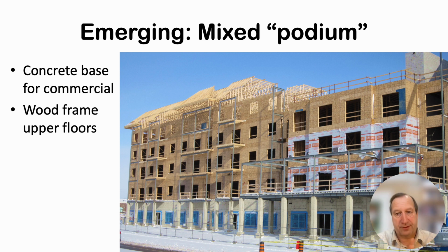Also emerging is this mix of using, say, concrete on the first floor or two, and that first floor might have more high fire risk activities. It may also have things like car parking, which is a high fire risk activity. And then from that floor above, that first floor called a podium, we will build three, four, five floors of wood framing on top of it. So these are mixed and fulfilling needs that we have right now.